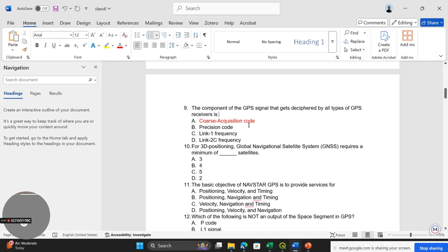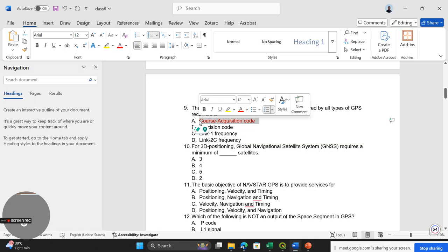Yes. So this is just a theoretical question only. So we have first carrier waves, which are L1, L2, L5. Then the GPS signal, which is carried with these carrier waves. So it can be a CA code, it can be a P(Y) code or L2C code or L2CM code. So you just have to go through it. So this CA code is available for L1 also, L2 also, and it can be accessible through all the receivers. Okay, so you just have to remember this thing and the combination of it. So you have to see various satellites and you just check the combination.